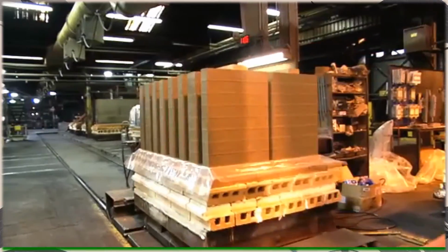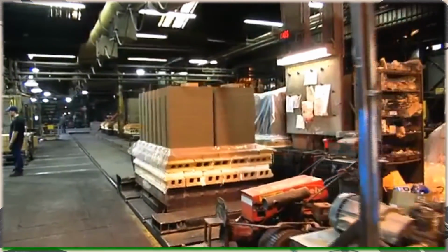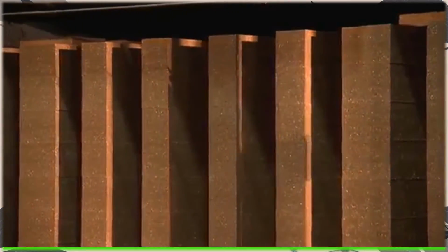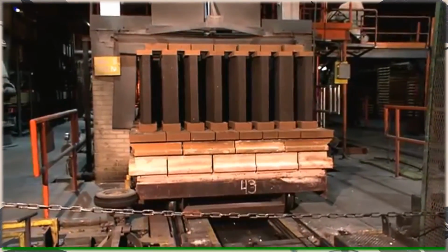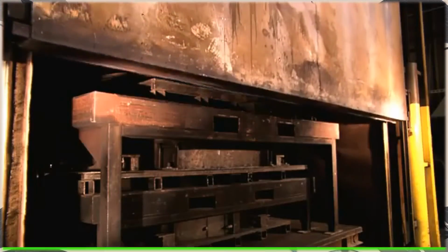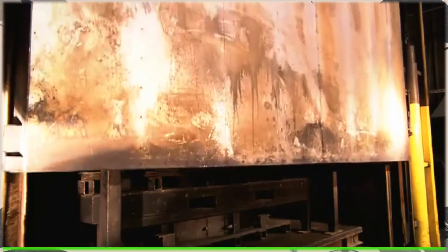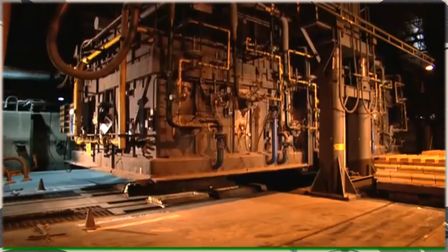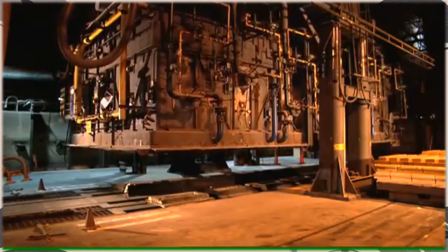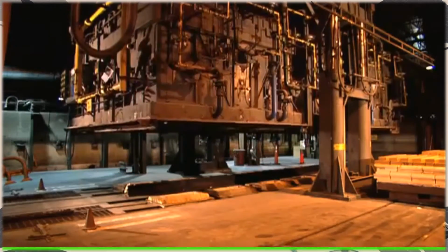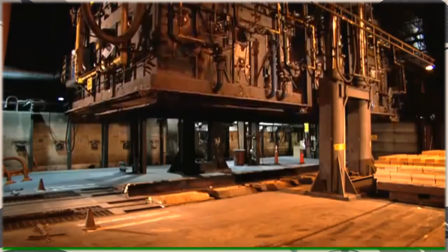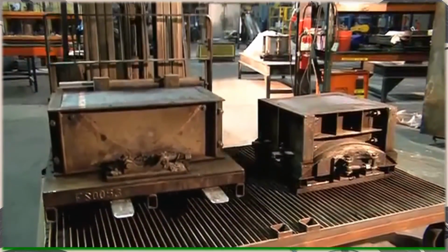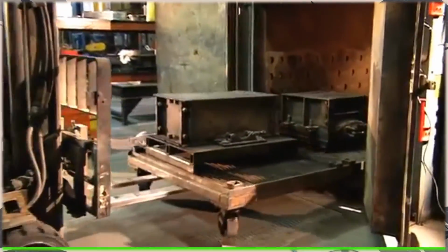Bricks and shapes are loaded on cars similar to small railroad cars, and then the cars are pushed into the front end of the kiln. As one car enters the kiln, one car exits the kiln at the back end. Periodic kilns are typically used to process small quantities of materials or large odd-shaped products. They are loaded when cool and then heated to a specified temperature for the time required. Material is removed after the kiln is cooled and the cycle is then repeated. Some refractory applications simply require low temperature treatment to set a chemical bond prior to installation and use.